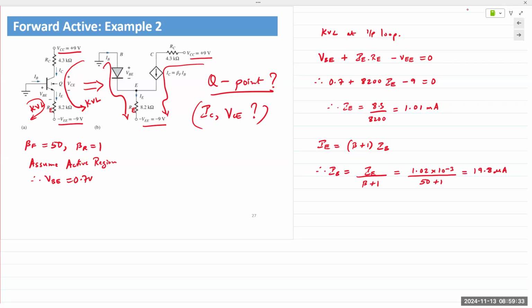If you obtain a slightly higher value, 10 raised to minus 6, 10 raised to minus 5 is reasonable, even 10 raised to minus 4 on occasion, but IB would not be more than that. IB is typically in microamps. A quick verification check is if IB is not in the 10 raised to minus 5 or 10 raised to minus 6 range, then it's probably not correct, and there's an error somewhere in your calculations. And of course, IE is the largest of all three currents.